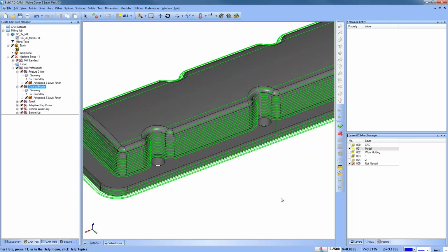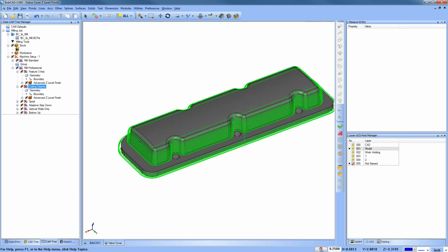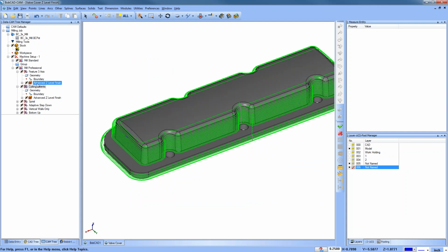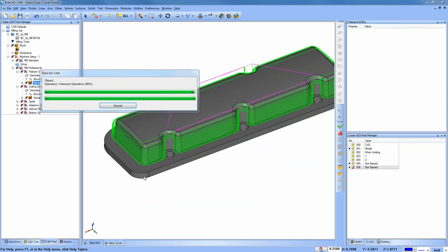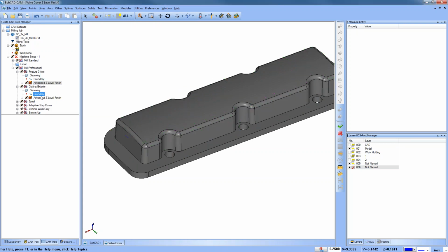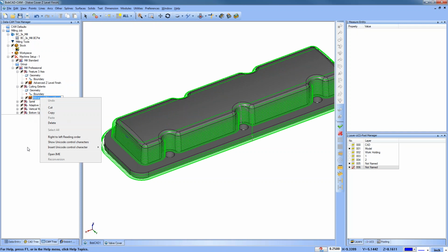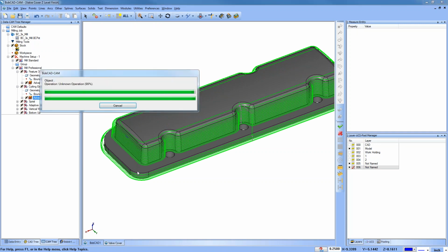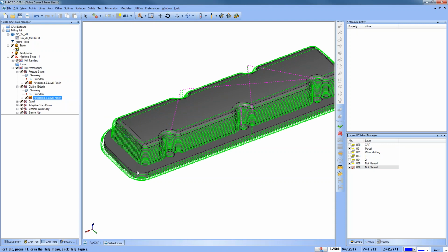Let's say the toolpath is going down in there and we check that and it didn't work. It didn't stop it from going down in there. The next step would be to plug the holes. This is generally what I'll do: I'll plug the holes, and I'll show you what I mean. I'll recompute. That's the wrong one. Hold on. Cancel. Okay. I will recompute the toolpath here, and we'll see the toolpath will go back down inside of that hole, okay?